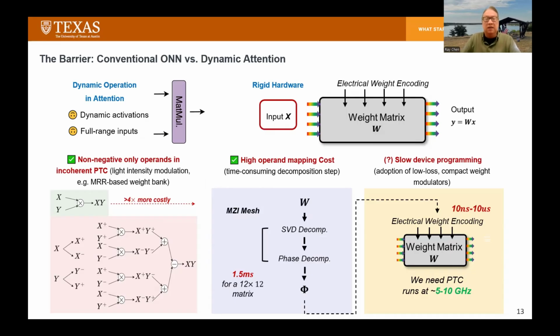To fully unlock dynamic operation of multi-operand MZI, we need high-speed modulators, which we will demonstrate in the coming slides and also in the coming months. We're still taking the full data. For example, a Kerr effect-based device could provide the required second-order response at much higher bandwidth, but the fabrication and low tuning efficiency are also considerations.